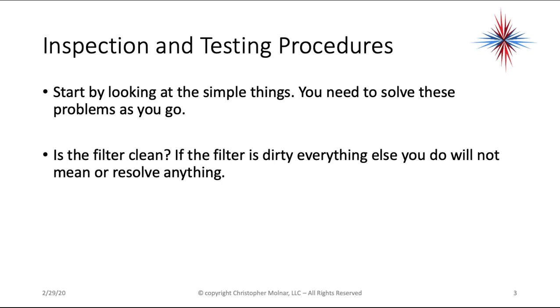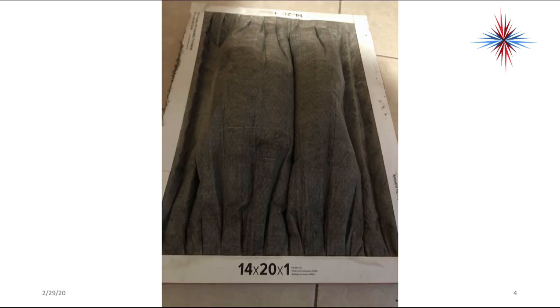For example, is the filter clean? If the filter's dirty, everything else you do will not mean or resolve anything. So start off, is the filter dirty? This is an example of a dirty filter. Okay, this filter caused over $25,000 worth of damage in a home. Okay, so just keep this stuff in mind.